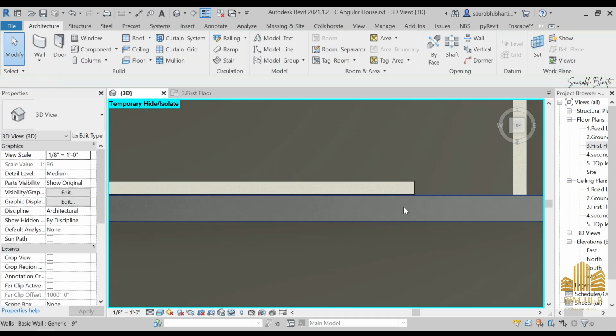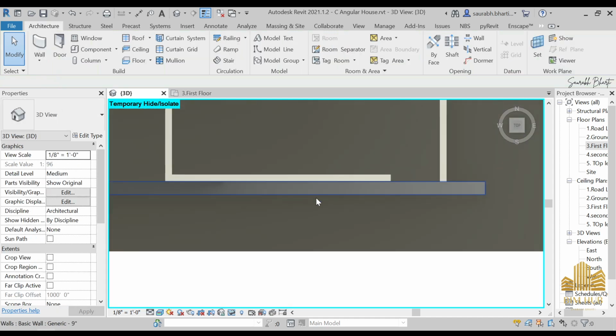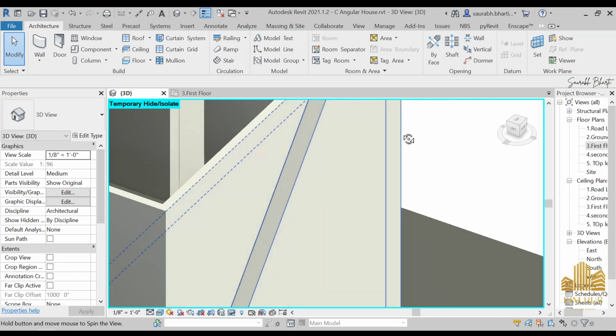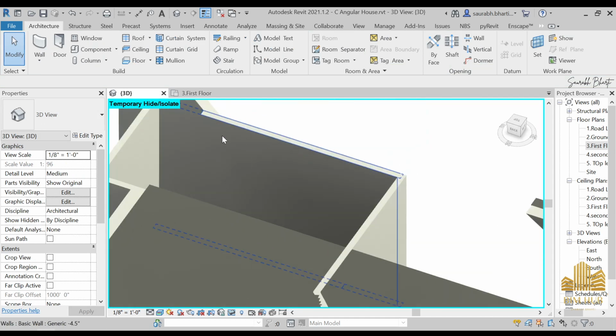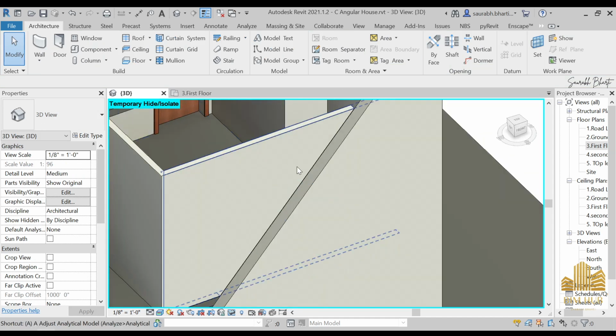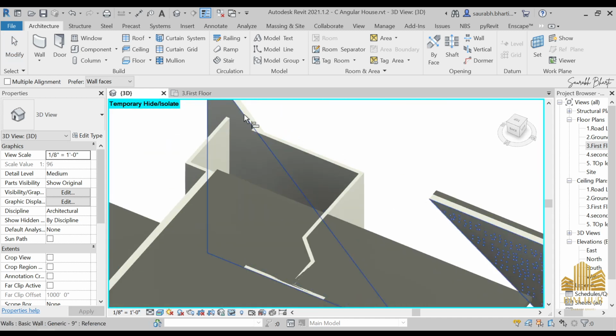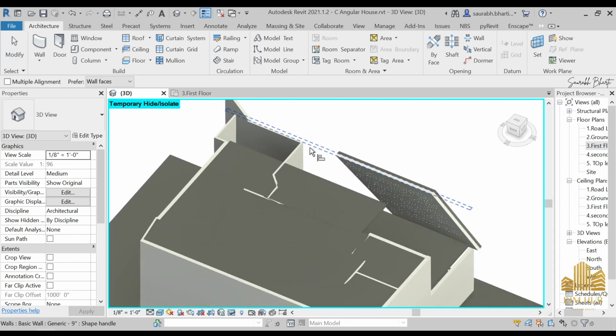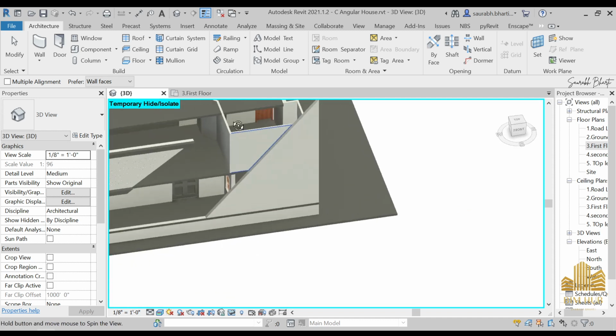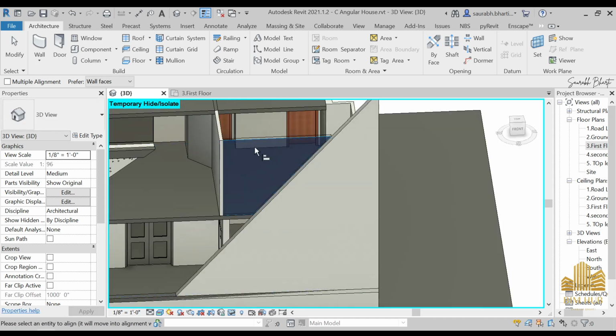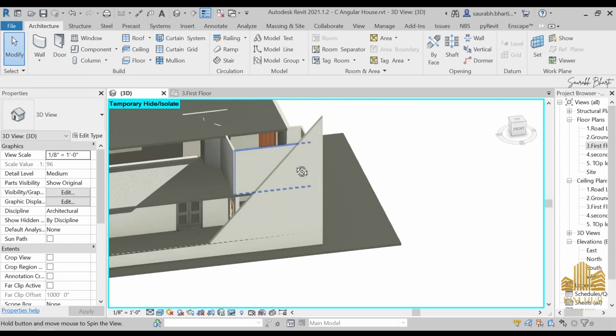and move it a little bit, or you can just align it. Okay, that is also an option, so you can align it. AL is the align shortcut. Select this face. Okay, and then select this front face, and now we have this portion as aligned portion.